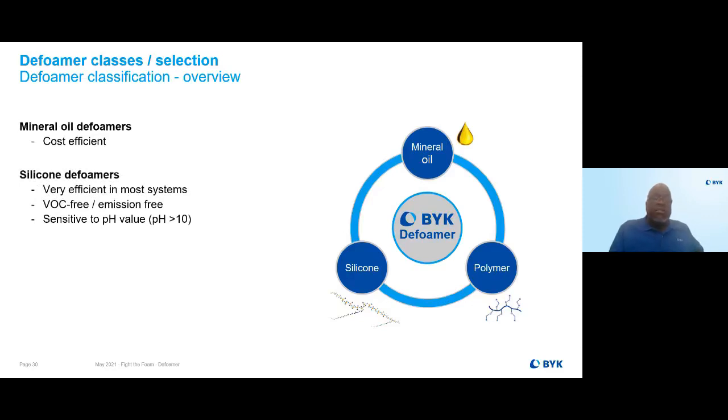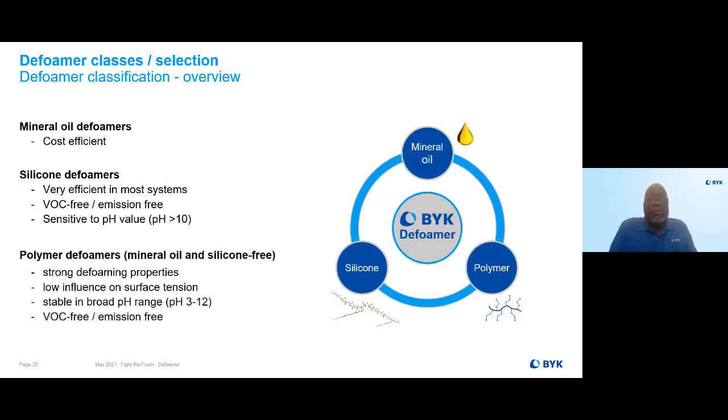And then the silicone defoamers are very effective in many systems. They are VOC and emission free, but they can be sensitive to pH above 10. And then there's the specialty or polymer formulas, and they can be a combination of mineral oil.